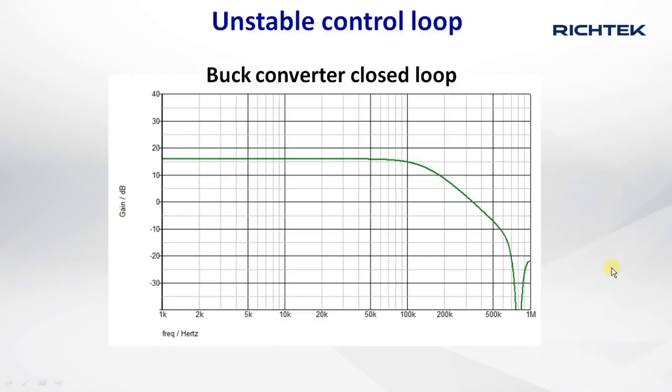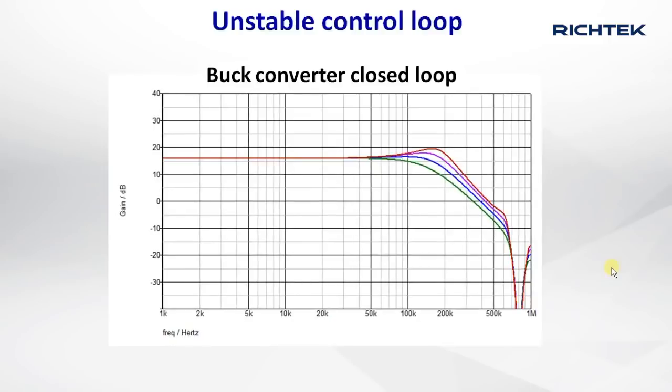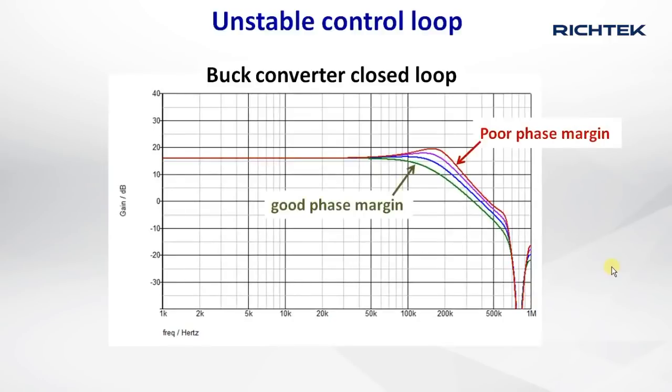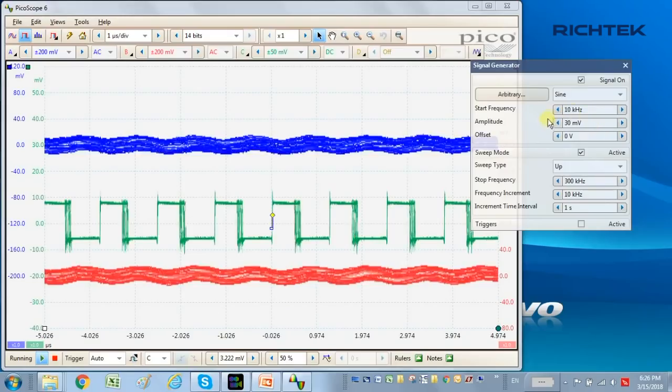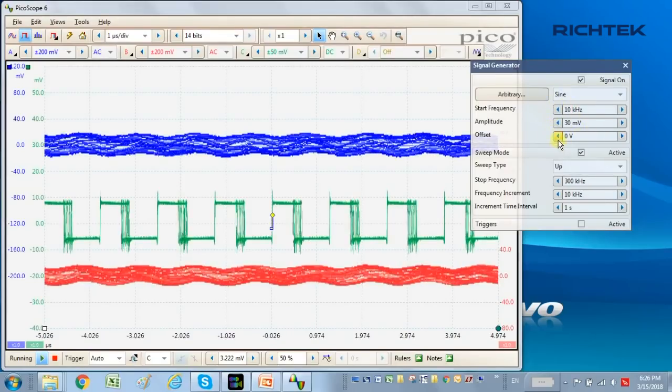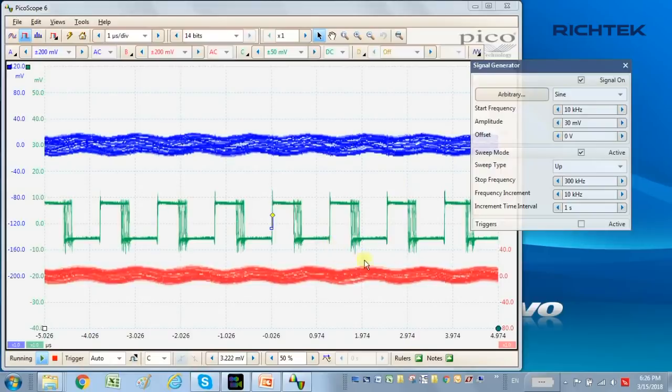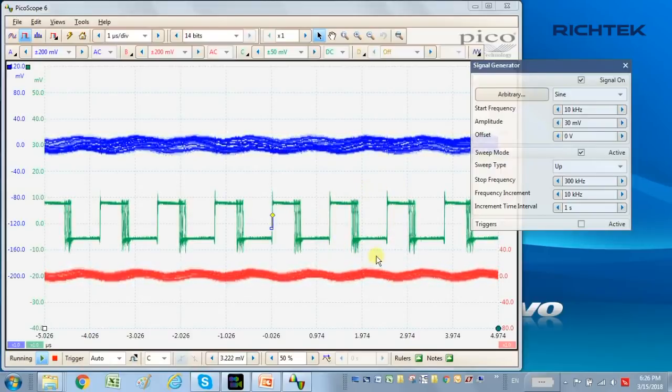Due to the lower phase margin, the converter will now show a tendency to oscillate around the crossover frequency. This results in peaking of the stimulus signal around this frequency and leads to a larger duty cycle variation. For accurate results, we need to reduce the stimulus more to keep the duty cycle variation moderate. In this case, I reduced the stimulus to around 30 mV peak.